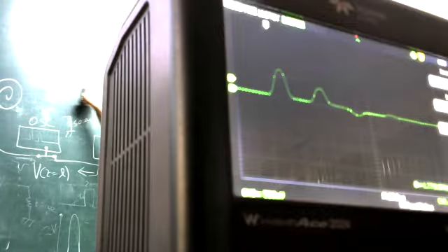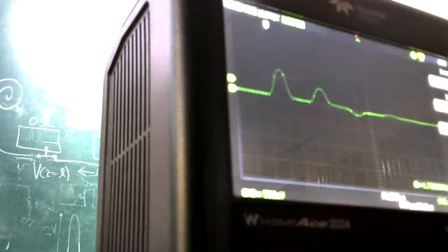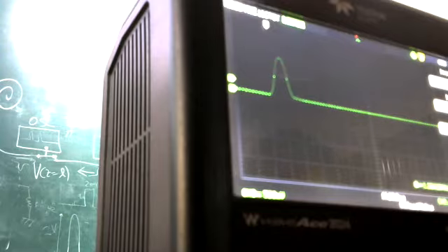Now, when we have 250 ohms, it's V0 into 1/3. But remember, V0 is the original V0, and the matched value was V0 over 2. So how do you go from V0 over 2 to V0 over 3? Multiply by 2/3. That's why the first pulse now is 2/3 of the first pulse in the matched configuration, and it's 1/3 of the 1 mega ohm situation.